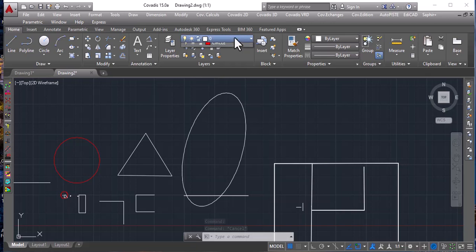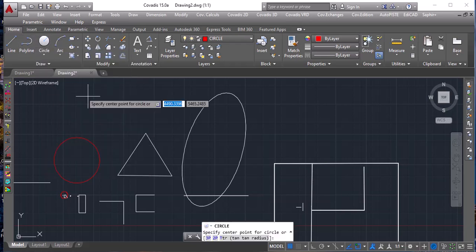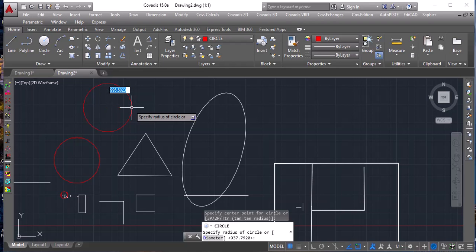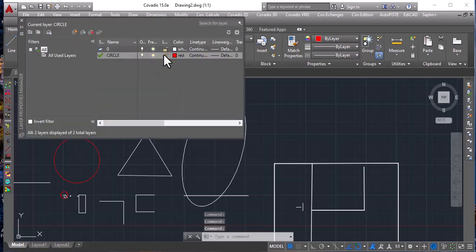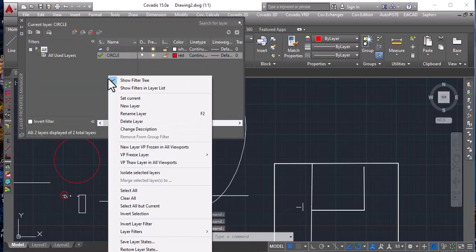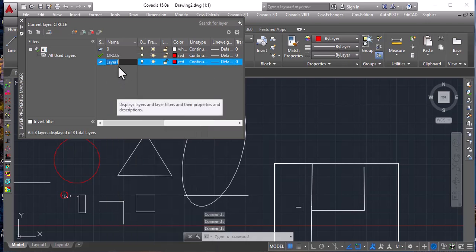Now, I can also select the layer and make it current. Anything I draw from now henceforth goes in the current layer. So either an element has already been drawn, which you bring back to a given layer, or you make the layer current and you draw the element. So those are the two ways. So if you've not seen how to create layers, you are going to create another layer. So I click new layer, triangle.